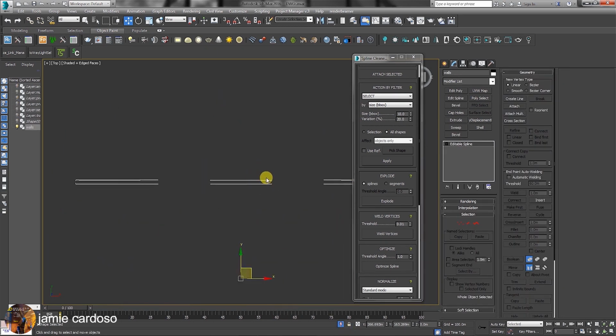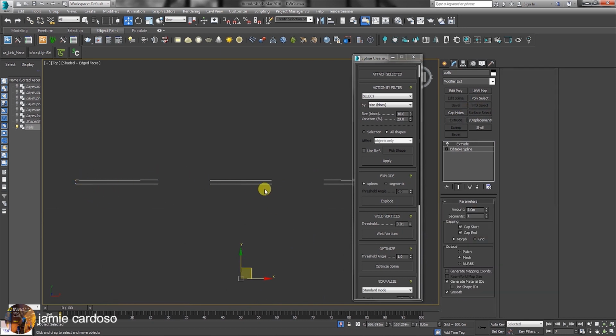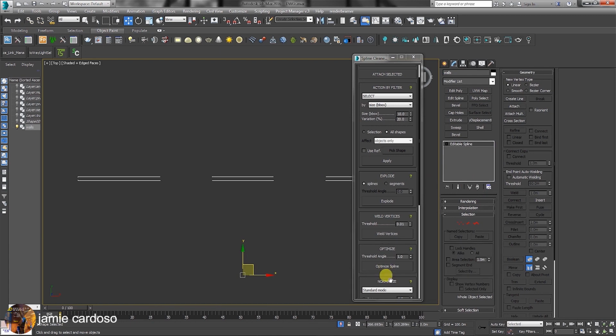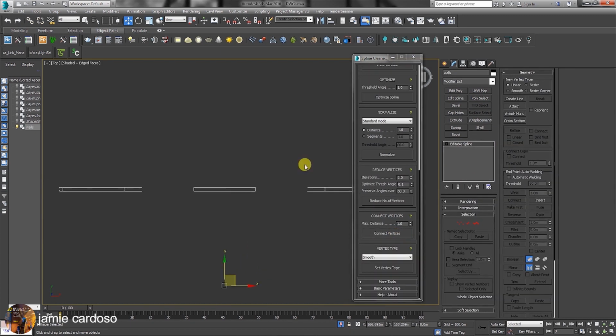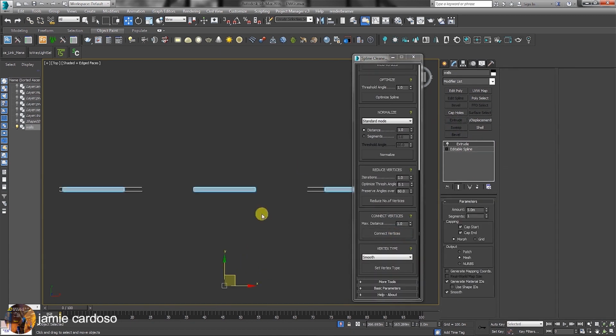Here's another drawing spline with missing segments. If you were to extrude as it currently is, we would have had similar problems as before. In this instance, we have a clear gap between splines. To correct the problem, delete the extrusion and click to connect vertices and extrude the spline again. The wall is now extruded properly. This is how I would normally avoid spending time retracing the drawing to create a new surface.